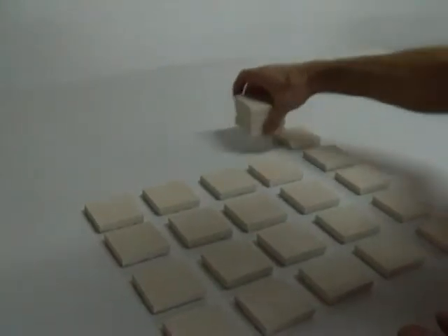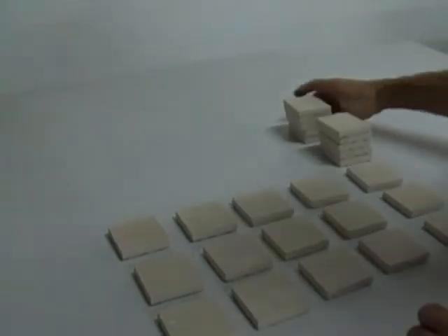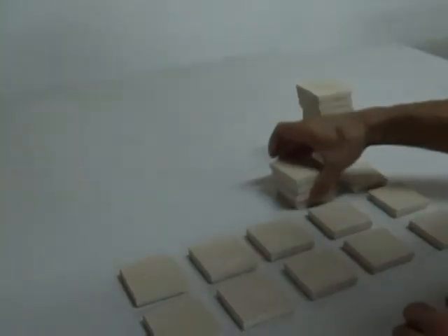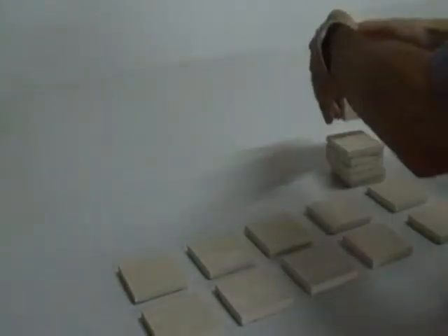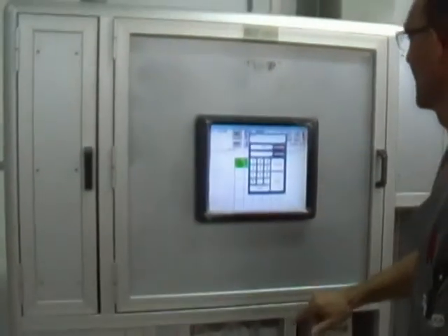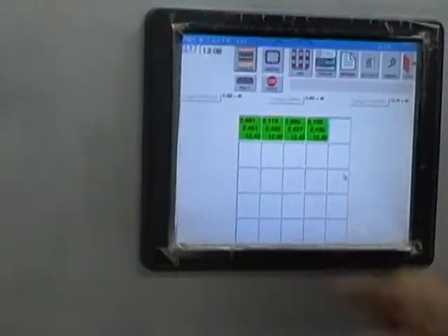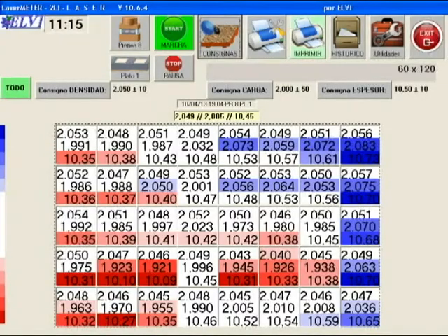To make the measurement, we take each green tile and we cut it in rows and columns in a representative number of pieces. We put those pieces in order and insert them in the pieces distributor. We select the press and pressing plate numbers and press the start button. At the end of the measurement, the results obtained in each test are stored in a historic and can be collected and analyzed at will.